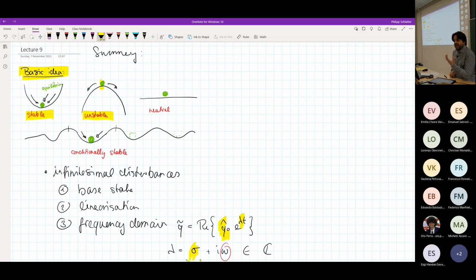Of course, the main different location in phase space would be that it goes from the laminar flow to the turbulent flow. That's what is most important for us from an engineering point of view, because we would like to be able to determine when we have transition to turbulence. And transition to turbulence is always initiated by an instability somewhere in the flow, something that is growing, departing away from the laminar state.